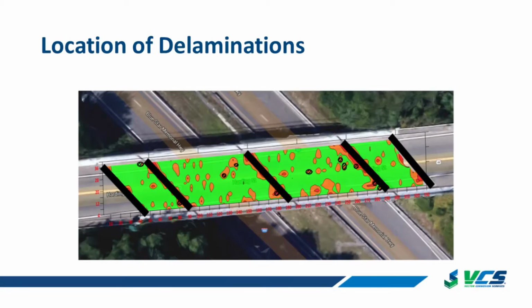And you can see this is just a highlight scale. So effectively, green is like over 4,000 PSI concrete. Yellow and reds are less. And we can see that the concrete's really weak around these large delamination areas. And so we have identified that, okay, well, if we start chipping these areas out, it's going to grow quite significantly because we've got low, weak concrete.